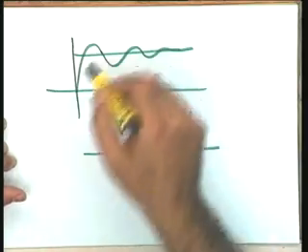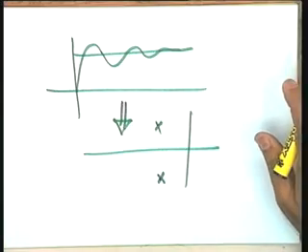Okay, so this concludes that shaping the dynamic response through the feedback action is possible if I appropriately design the controller and hence the numerator and denominator polynomials of D(s), so that the closed loop poles of M(s) are the same as the closed loop poles which result in the required dynamic shape. But one thing is there, my friends. If really this is the objective, I can realize this objective. This statement I re-emphasize, and if this is the objective, probably this objective can be realized in a very simple way in the open loop control mode itself. Can you suggest how can I realize this objective?